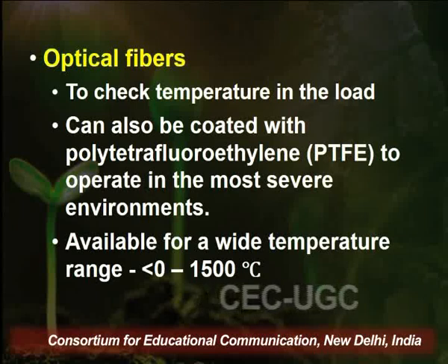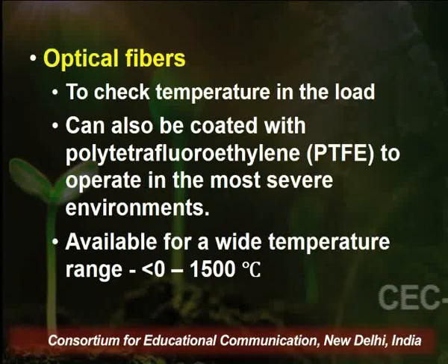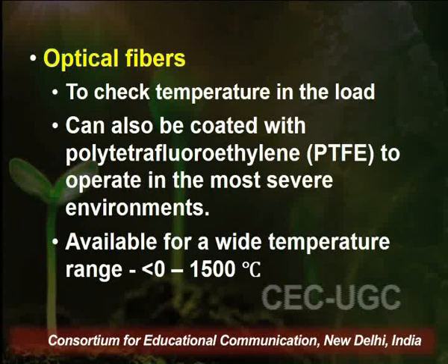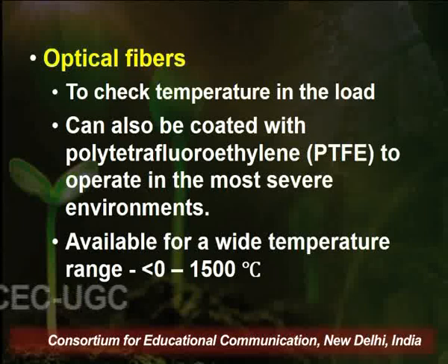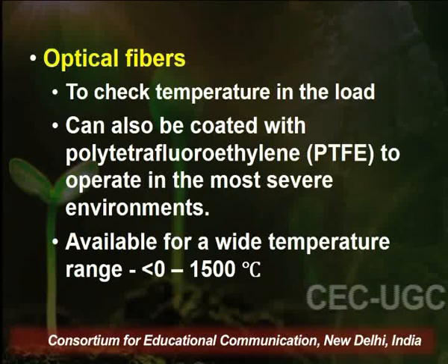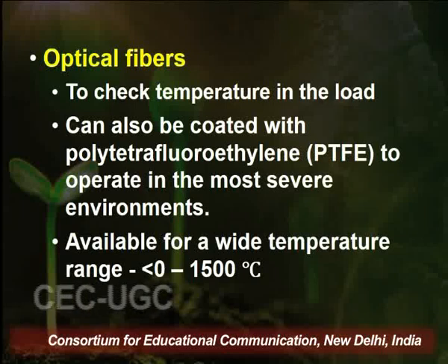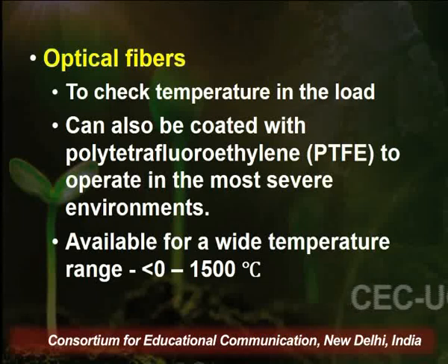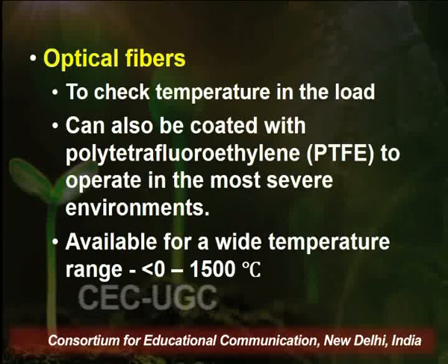Second, in carrying out the temperature measurements with optical fibers, many a times it has been observed that certain reactions produce a certain corrosive environment inside the microwave. Or whenever you are extracting a particular herbal drug material with a solvent, it may provide a certain harsh environment inside the extraction cavities. And these optical fibers, since they are the contact type of thermal sensors, have to withstand those harsh conditions, and therefore sometimes they are coated with polytetrafluoroethylene, that is PTFE, in order to protect these fibers from those harsh conditions or environments.